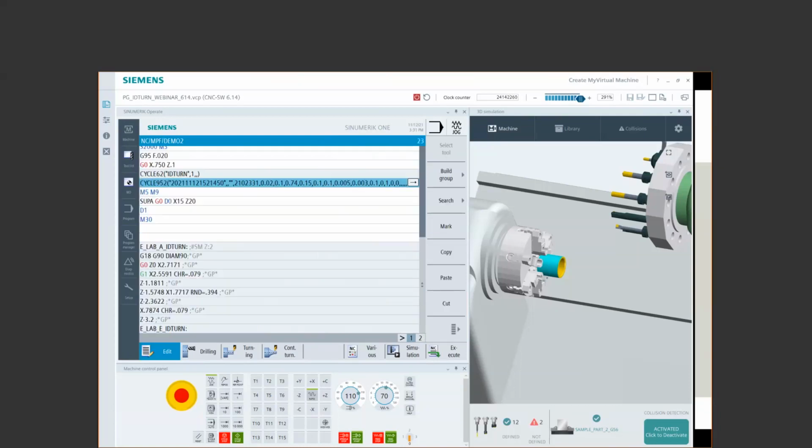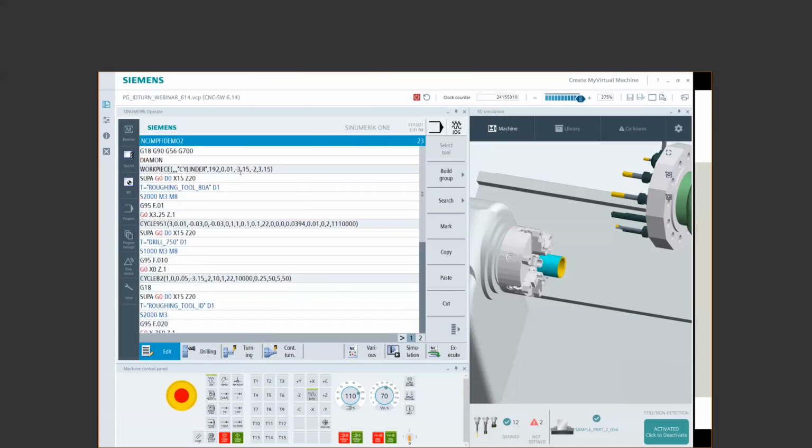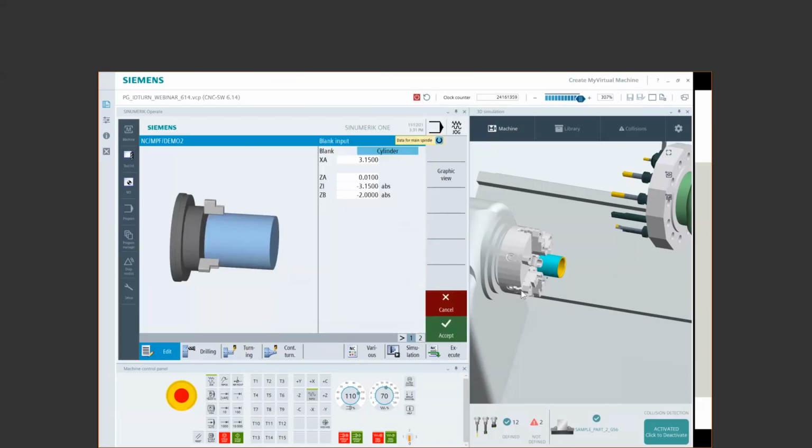All right. Are there any ways to describe customized workpieces in the beginning of the program? If you're referring to our workpiece blank, unfortunately, no. When I get to this machine space model, this is an STL file, so I can make it look like anything I want it to look like. But when it comes to the standard simulation, you are limited to your basic primitives here: cylinders, pipes, blocks, and hex stock would be your basic primitives for graphics.